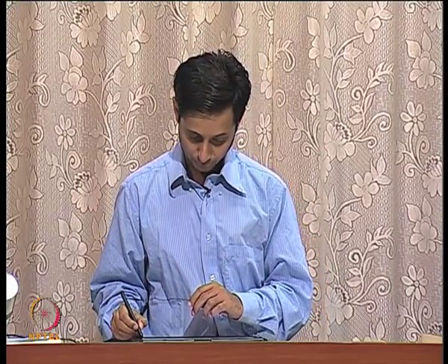So, we have figured out that a wire is really something else. It is not a short circuit, it has some inductance per unit length, some capacitance per unit length, and some resistance per unit length. Suppose the dielectric material was conductive a little bit.